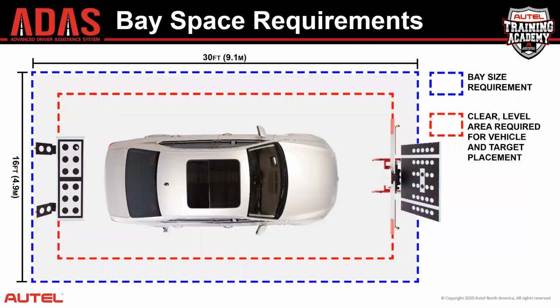Then you have to consider bay space in your shop. Now, the bay space requirements for an ADAS calibration are determined by the OE. They set the space requirements, they set the target height and the target distance. But generally speaking, you can perform most ADAS calibrations in a standard 16 by 30 foot service bay.